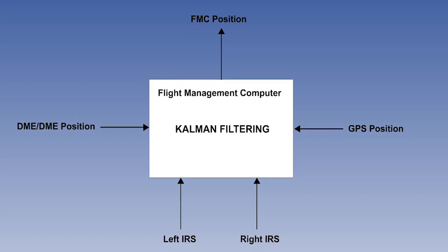The later generation of inertial systems, which are generally known as Inertial Reference Systems, or IRS, are usually part of an integrated Flight Management System, FMS. In the Flight Management Computer, or FMC, there are usually 2 or 3 IRSs, each generating its own present position. These IRS positions are compared with independent sources, such as Global Positioning System or GPS, and computer-generated calculation of crosscut positions, which have been obtained from ground-based radio beacons called distance measuring equipment.